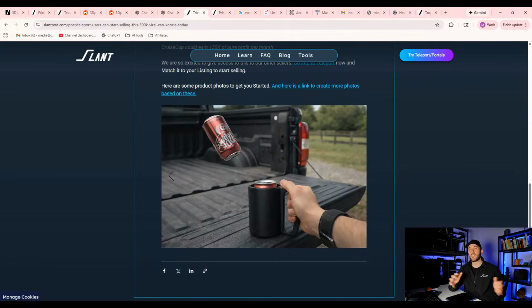That's all it's supposed to do. That means that if one of the 200 settings inside of a slicer is different from one slicer to the next, or if the material is different, or if the machine is slightly different, or if the rotation of the earth is different, the slicer settings are not robust. They do not work on every printer, every place, every setting, everywhere. So it is better to design any given part so that it can work on any slicer, on any machine, at any time.